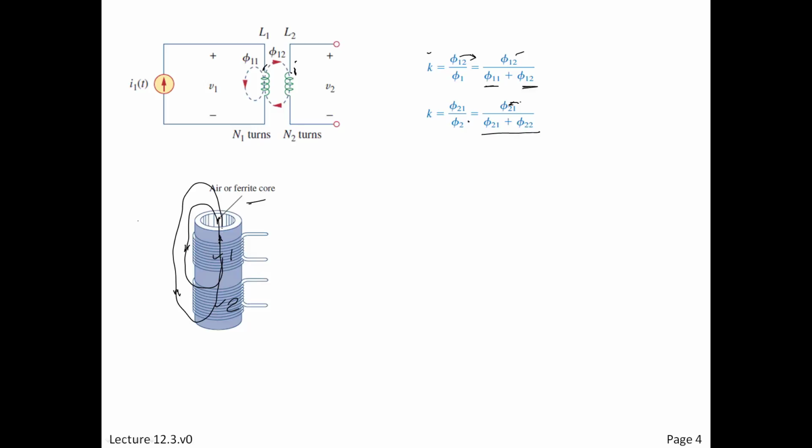The stronger magnetic fields are going to stay closer to the coil in this arrangement. They always do. And the weaker ones, the ones that have to reach the farthest, are the ones that are going to intersect too. So the coupling of that arrangement is going to be, just by inspection, kind of low, because these two terms we talked about, Phi12 and Phi21, are going to be a small portion. You can just see that physically.